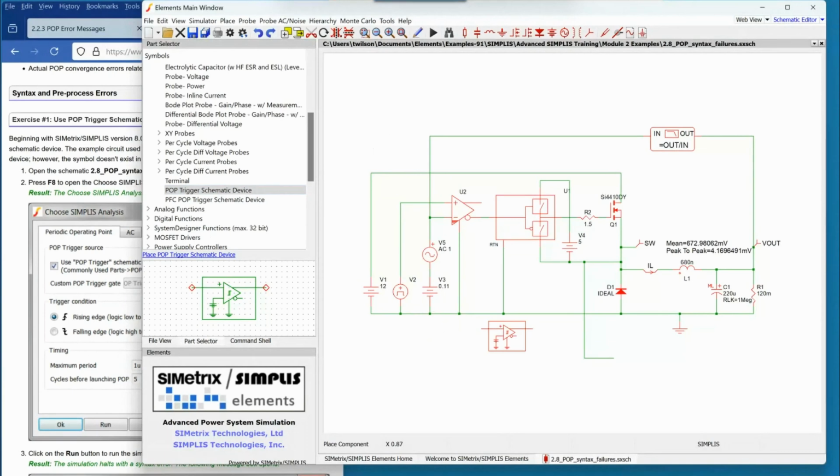So now the question is, where do we hook this up? And we happen to notice, oh, this looks tempting. What's it connected to? Well, it's connected to the switch node. Okay, that sounds reasonable. One thing about switch nodes is that they're often very noisy. So depending on the thresholds and everything, you may have some double pulsing going on or just some ringing.